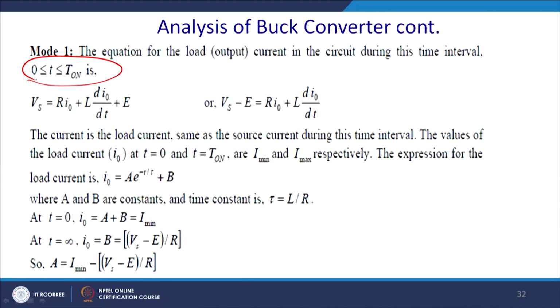So, we shall write the equation for T on, when the switch is on. The equation of the load current during this interval is Vs equal to R I0 plus L dI0 by dt plus the back EMF. You can take the back EMF or the battery voltage on this side, rewrite these equations, and solve this equation. Ultimately, it will be a first order differential equation, and any first order differential equation is an initial value problem.